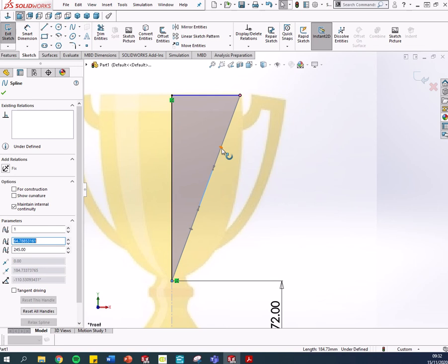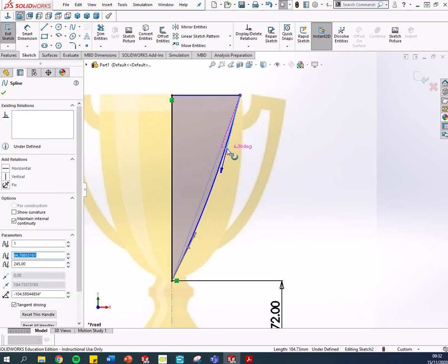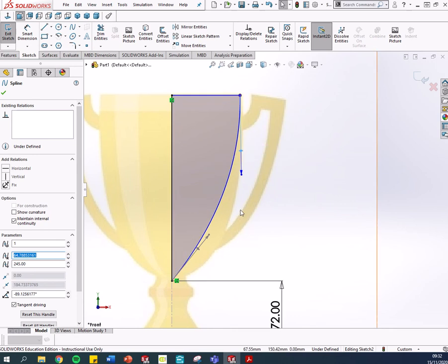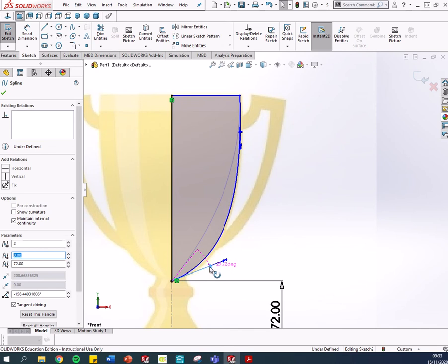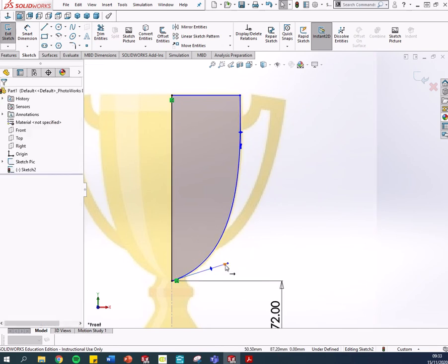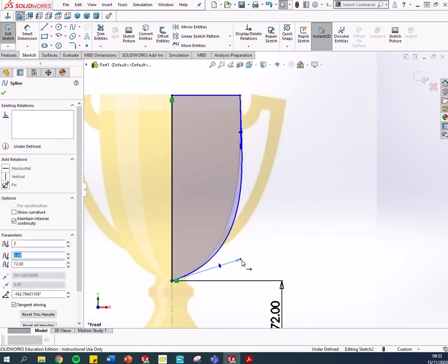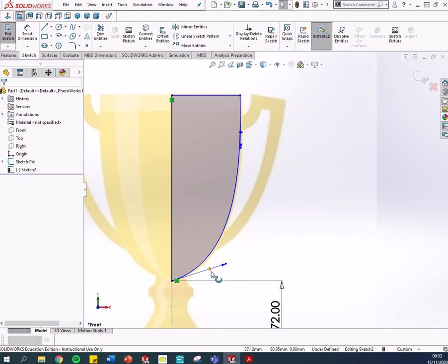The diamond adjusts the length of the spline, sorry, adjusts the angle of the spline. So watch, I'm just dragging it out there, like so, and I can drag it to meet the curvature of it. Same down here, it's the diamond we drag to change the angle and get the curvature. What the triangle does is add more length to the spline. It's like it gives it more rope. If you think of it like a piece of rope, it adds more to it. Don't use it too often, it's more to do with the diamond that we manipulate our spline handles.